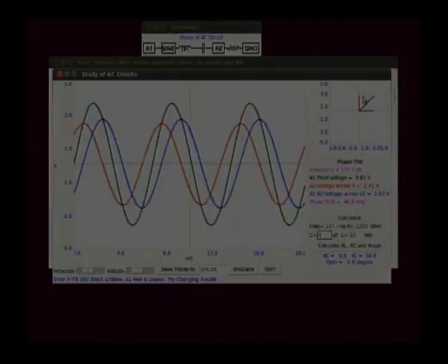Now, if you look at the screen, the net result is capacitive. You can see the current is ahead of the total voltage. And if you try to calculate the value, let us put the capacitor as 1 microfarad. It says the phase shift is 45.8 degrees and our measured value is 46.5. So, these are well within the tolerance of the capacitance and the inductance used.